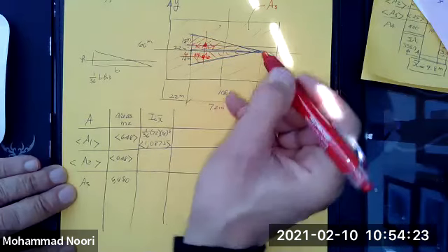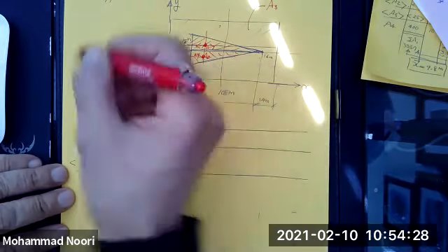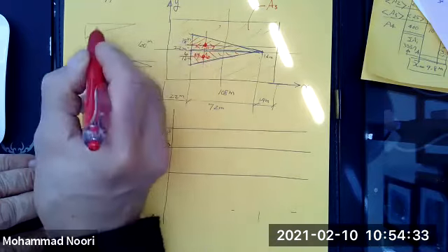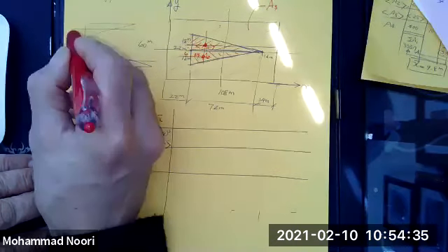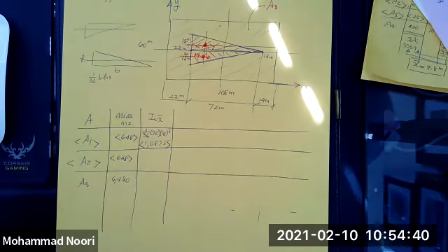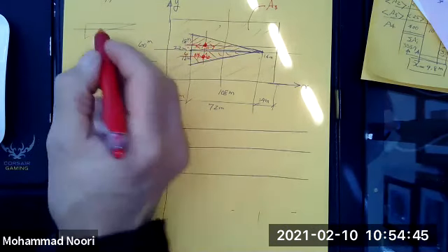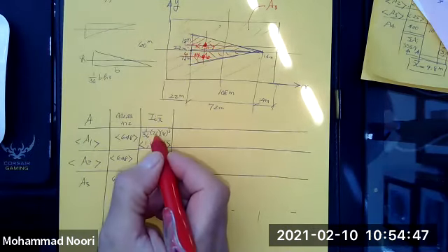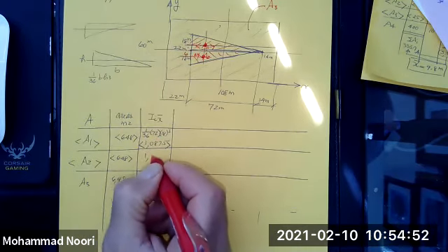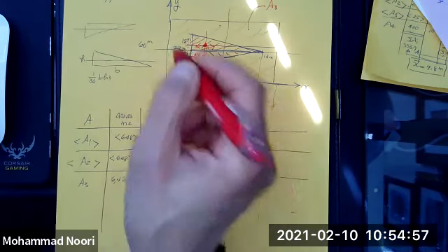Moment of inertia about this centroidal axis, which is basically kind of reversed. That's it. So you're trying to find the moment of inertia about this axis with respect to its centroidal axis, which is again 1/36 of base, which is the same, 72 times height cubed. So it would be the same value. How about for this one?